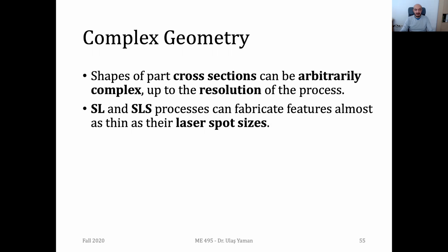So considering complex geometry, we were talking about design for additive manufacturing, if you remember. So you need to know all these issues while designing parts for your additive manufacturing machinery. One of the capabilities, if you remember, is to fabricate complicated geometries, and this is not possible, as you know, in conventional manufacturing. So if it's suitable for you, if it has advantages for your overall design, then you may go with complicated geometries. But if it's meaningless, then it's better to keep your design as simple as possible.